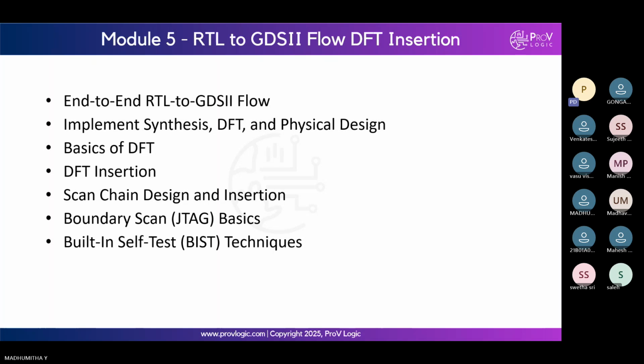This test pattern generation we will not do. That will be done by DFT engineers. They'll generate these test patterns and give them to us. So it is one of the inputs for physical design. We will insert this DFT in our design and run a design flow check on the netlist with the DFT.